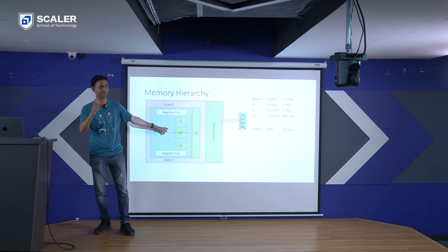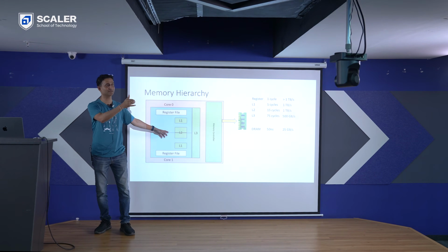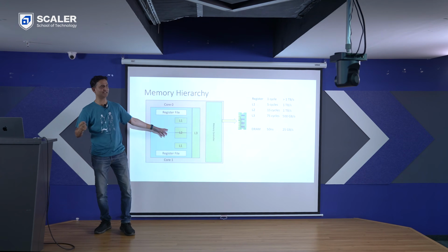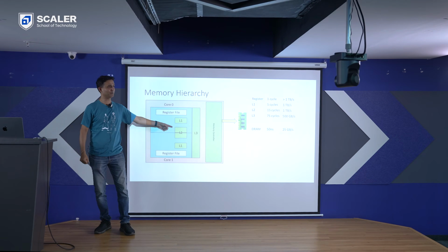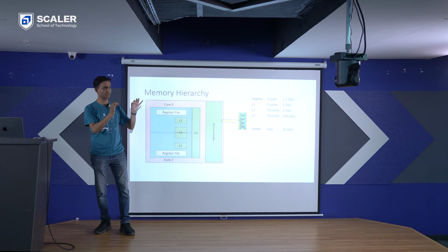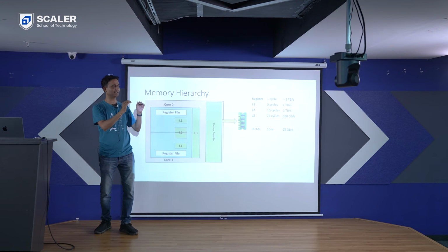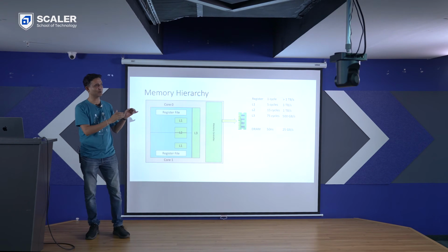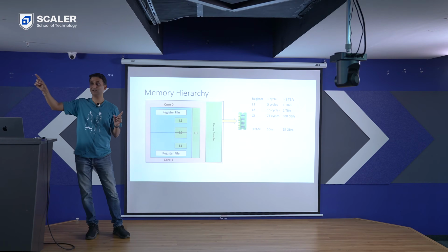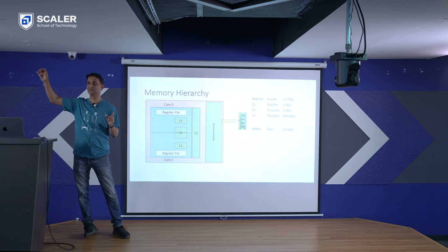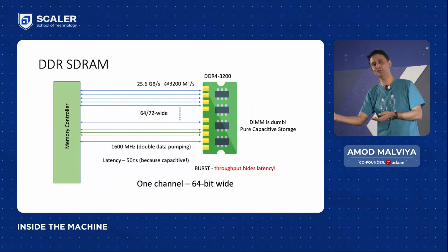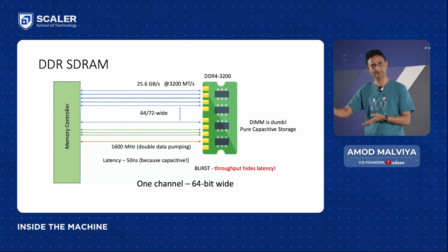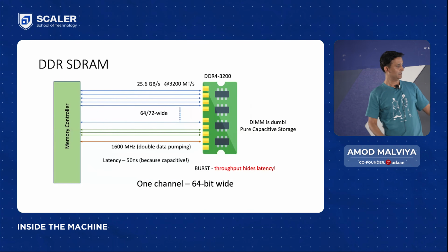SRAM, static RAM. When you do a read, there's nothing that needs to be refreshed. In the case of dynamic RAM, things need to be, because you discharge the capacitor. Because this is a pure logic circuit, it uses only transistors. There's no charging, discharging. Technically it's happening, but of a very different kind, whereas DRAM was capacitive. Capacitors are slow.